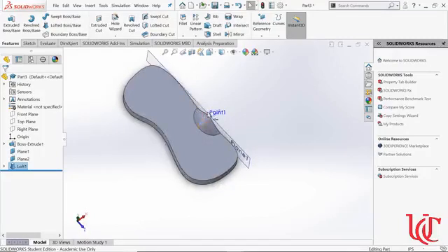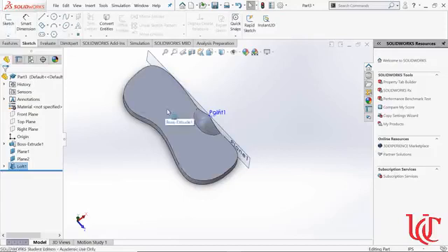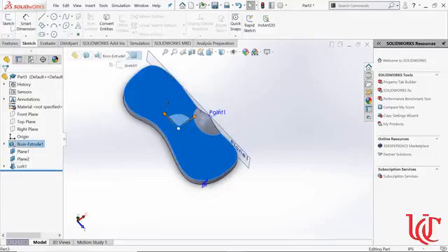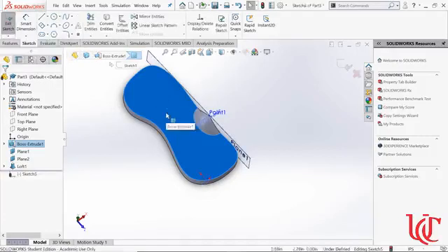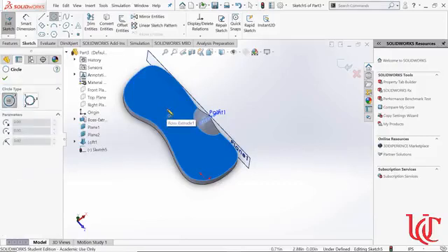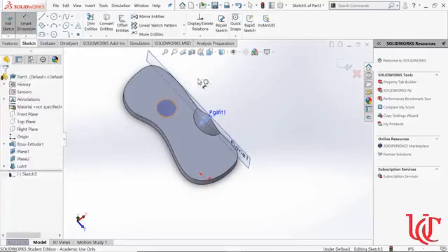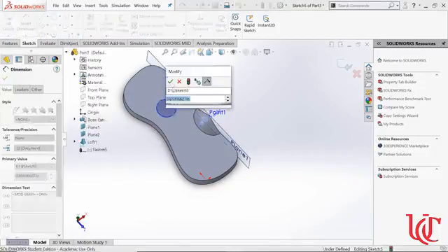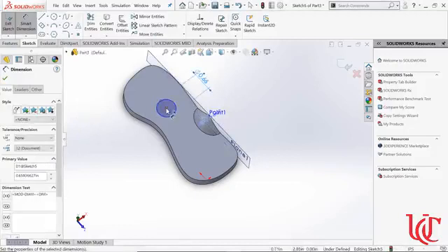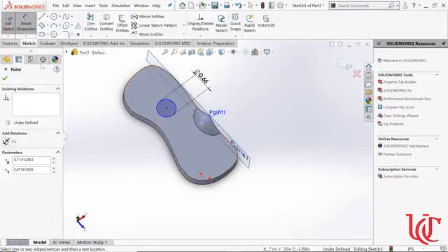Now, let's pretend I had wanted to cut away something from this. Again, that looks kind of funny. You could specify extra curves. I can make curves here and here as well, as what I wanted. All up to what you want to do for your shapes. Let's pretend I wanted to sketch. And again, I'm going to sketch on this plane. Sketch. And I'm going to make a circle here. And I'm going to dimension that circle. And I'm also going to dimension where that circle is compared to my origin.